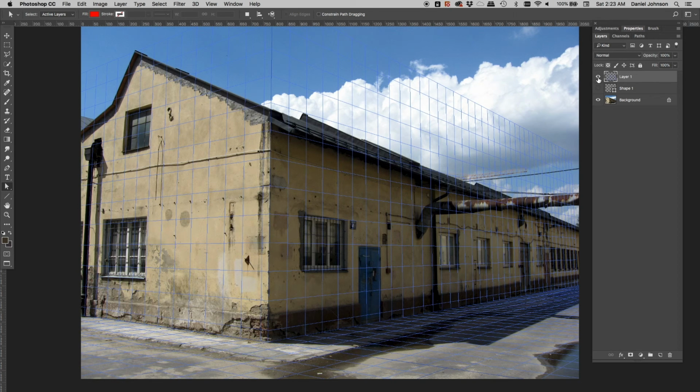So that can be pretty handy if you need this 3D grid for part of your design or as a foundation, or again, like I say, like 3D guidelines. That can be very helpful. But the important thing here is you have to do this on its own separate layer. If I had clicked on this layer here, it would have rendered the pixels of this grid, and these are just pixels, over this layer and done a permanent change and destroyed the pixels underneath.